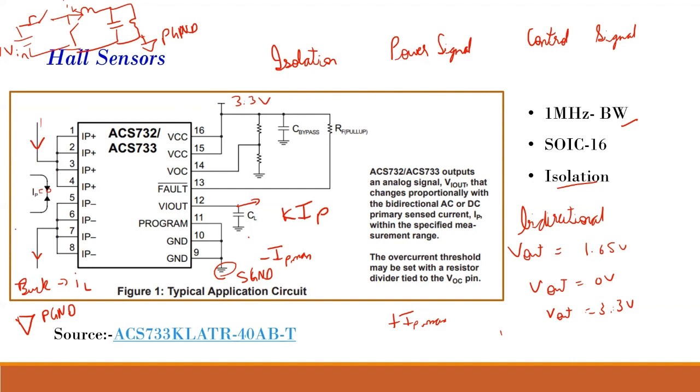Sir, anyway, when we are giving back the gate signal to the MOSFET, high side or low side MOSFET, again we will drive with respect to the power ground only. Suppose we are driving the low side MOSFET. Yes, you're correct. So in that case, we need an isolated gate driver. That driver is a different circuit now. It has a different ground. That will be a different driver.